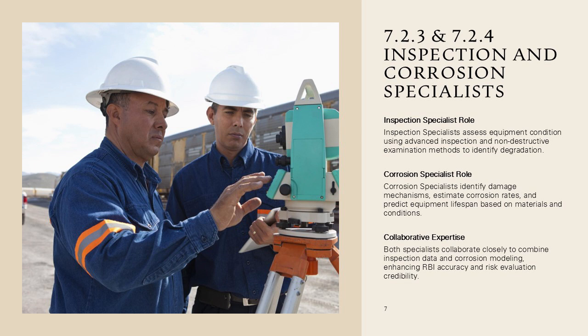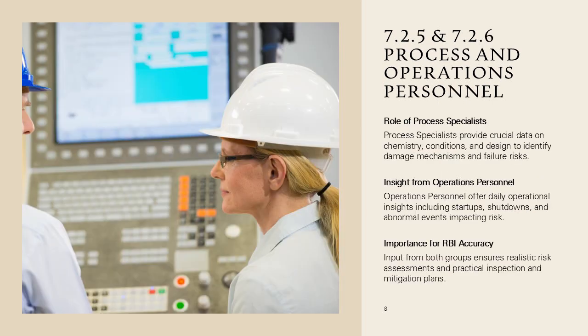Their combined input ensures that RBI assessments are grounded in realistic degradation behavior rather than generic assumptions, thereby improving the accuracy and credibility of risk evaluations. Process specialists and operations personnel provide essential context for RBI assessments, as described in API RP 580 sections 7.2.5 and 7.2.6. Their knowledge of how systems are designed, operated, and controlled is critical for understanding both the likelihood and consequences